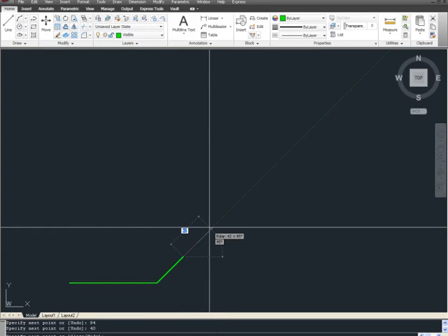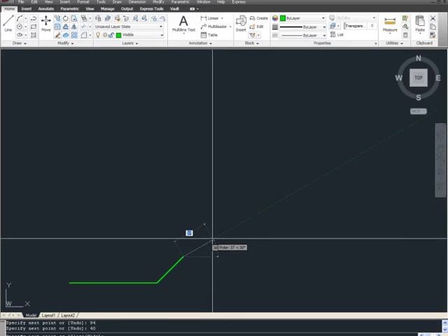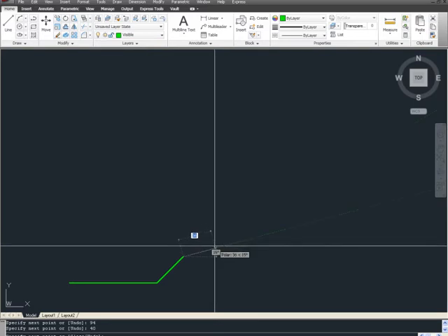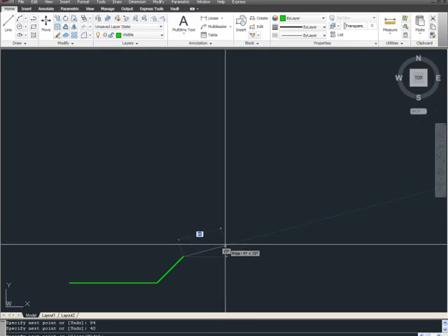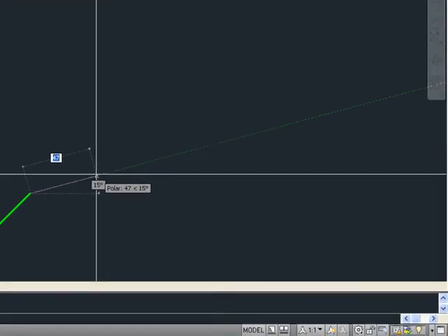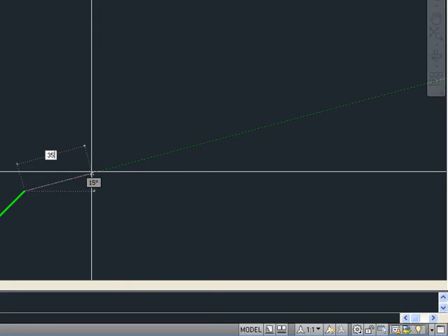So right now I have the cursor positioned so that I would be drawing a line away from the previously drawn line at 180 degrees. So let's back it off by 15, 30 degrees. So we've established the correct angle there, and the next line has to be drawn to 35 units. So I'll type that at the keyboard and press the Enter key.